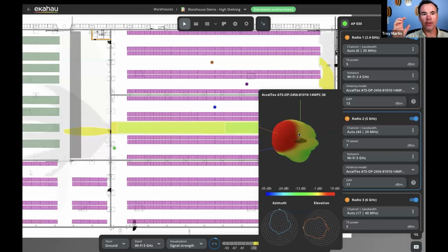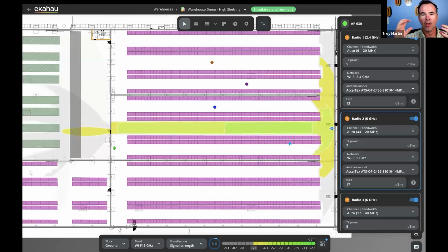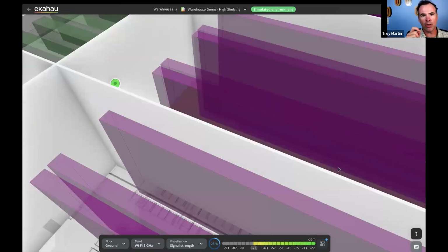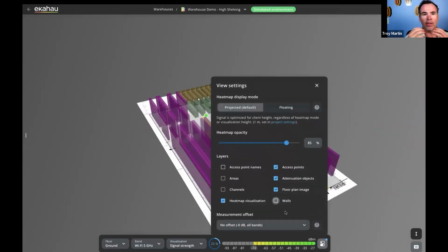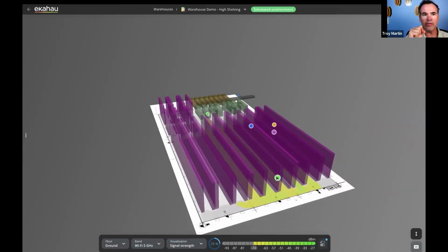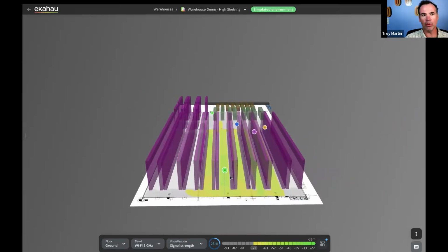Antennas are just changing the shape of that balloon. So the bigger the gain on the antenna, the more you're squeezing or focusing the balloon in a particular direction, but the actual volume isn't increasing. So when you're picking those different antennas, whether it's omni or highly directional, that's one thing to think about, is just how you're squeezing the volume of that balloon.